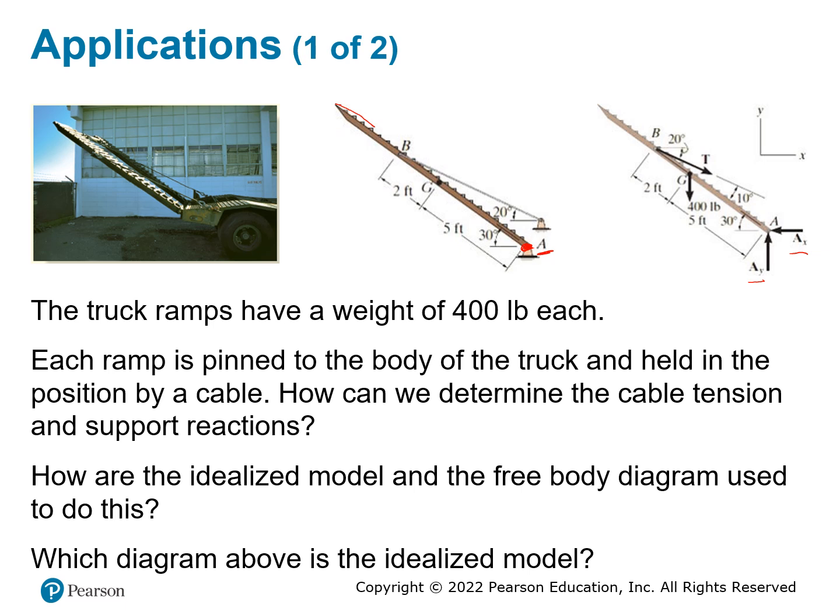So how do we idealize this model? How do we write an equation to model this? Here you can see there are several forces. We have the weight that we always have to consider. Pounds actually is a unit of weight. You have the gravity, which is simply the weight, and that's 400 pounds. You also have cables, and a cable always provides a tension. So this is the tension at the connecting point B. And then you have the pin, and we want this whole thing to be balanced.